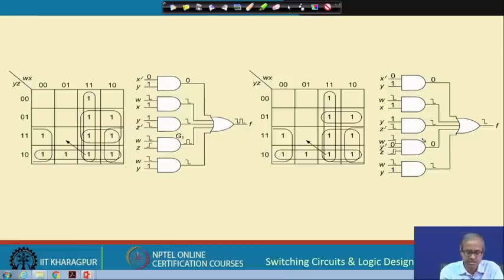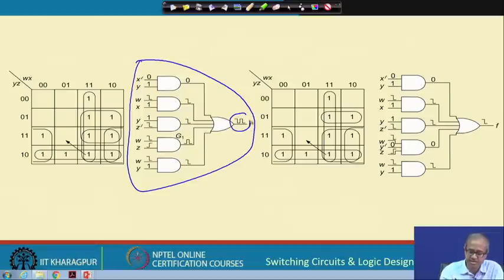This was your original implementation, which was resulting in a dynamic hazard in the output. Okay. Now, here what I am doing, instead of this WZ, here I have modified this. So, with this modification, you see in the output I am having a clean transition. So, the idea is this: you must prevent some of the transitions from happening. If you can do this, then the dynamic hazard in the output will be avoided.